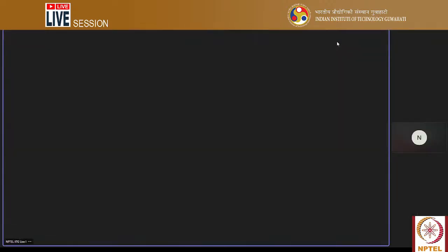These tools are getting advanced and they are coming up with very new ways of mapping things. There are a lot of ways you can map a design. I have taken a very small example, right? But think about 1 million gates there. There will be many ways you can map it, right? So it depends on how fast your algorithm is to identify the minimum LUTs to cover the entire design.